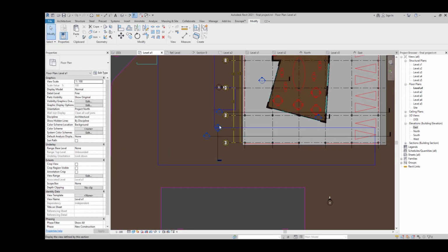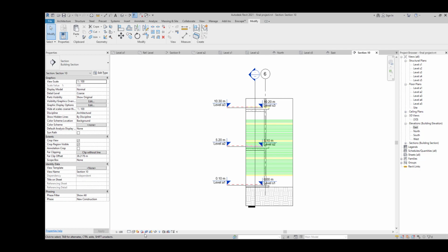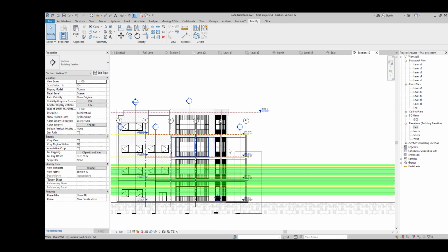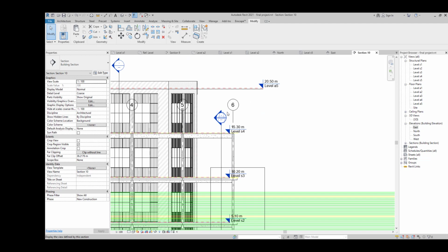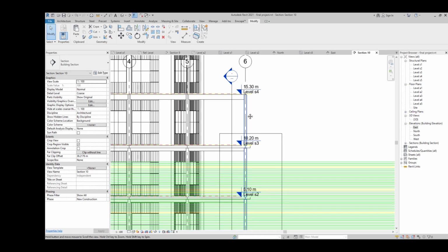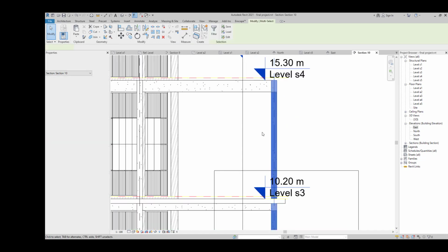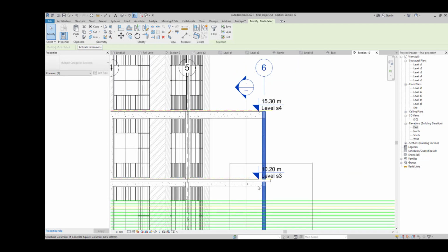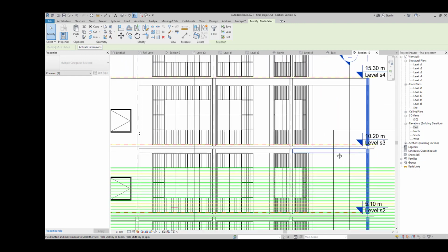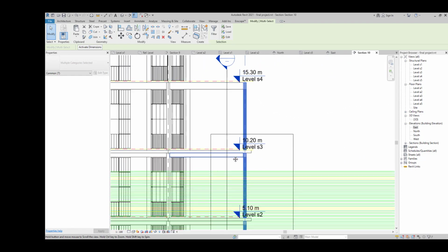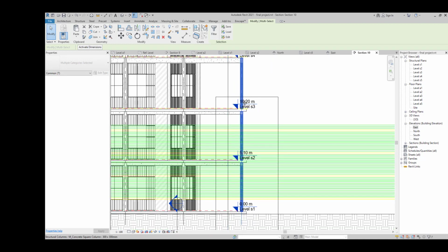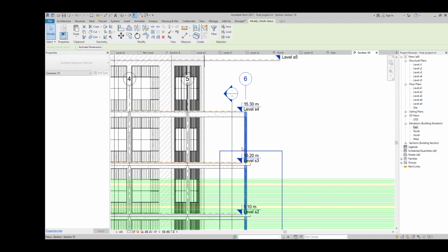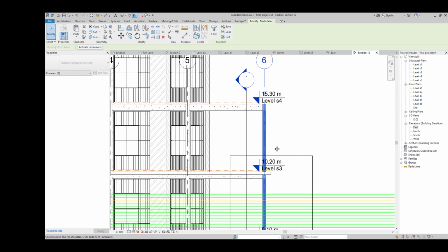After that I can go to my section line, select my columns from there, turning off the wireframe so I can see where my columns are right now. Here I can just grab them. So here we are going to face one problem, maybe we can say, because we extrude our column from the base to here. If you copy paste them, it's going to copy paste from the base as well. So we can do it and then we are going to attach base and it's not going to be any more problem.